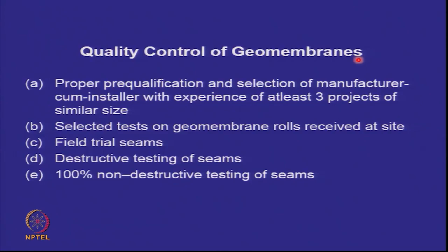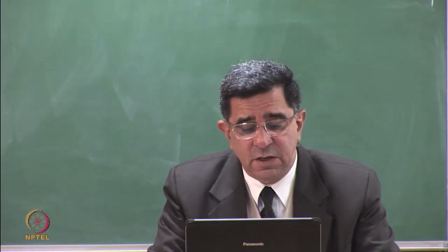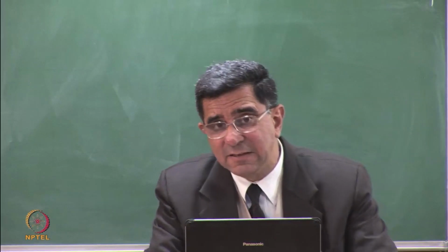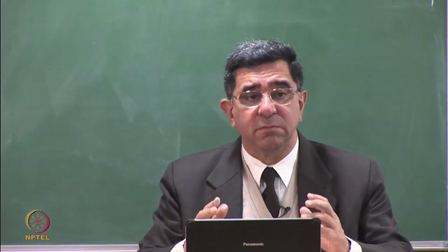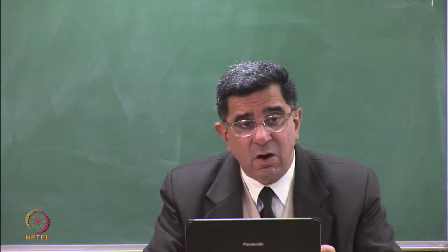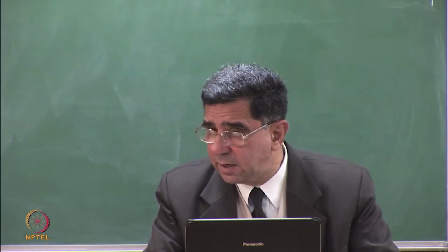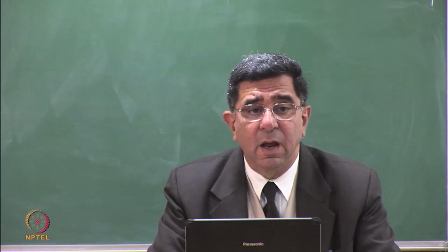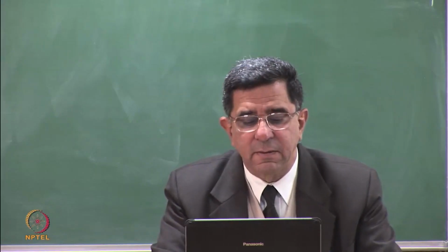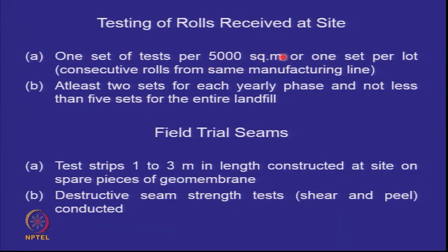So we have quality control in geomembranes as well. You must have a proper contractor who is supplying the geomembranes and has been doing projects for 3 years. You will do the tests on the rolls as received before they are installed, and then you will do the tests on the field installation. Some of them will be destructive testing and some of them will be non-destructive testing.